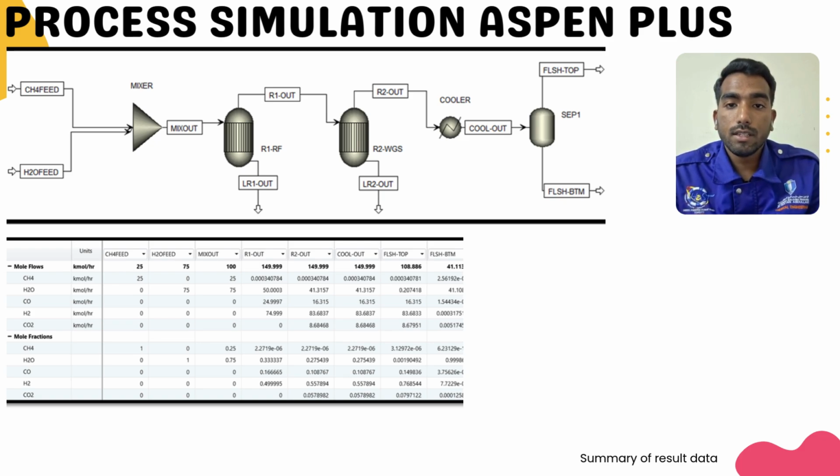it will enter the separator. The gas phase at the top is hydrogen rich with mole fraction about 0.76, while the liquid phase at the bottom is mostly condensed H2O and CO2. That's all from me. Thank you.